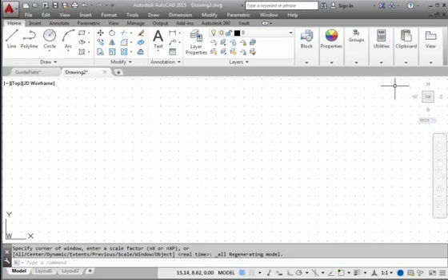In the previous drawing, the guide plate design, we have used the origin of the world coordinate system as the starting point. That approach is a very effective way in creating designs. There are other techniques we can use to create design. It is not really necessary to always start at the origin of the world coordinate system. For the spacer design, we will look at another technique which does not reference the origin of the world coordinate system. We will create the spacer in somewhat an arbitrary location on the screen.